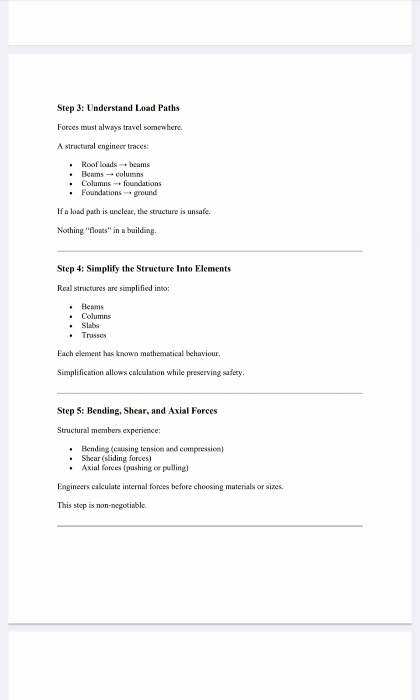Step 4, simplify the structure into elements. Real structures are simplified into beams, columns, slabs and trusses. Each element has known mathematical behavior. Simplifications allow calculation while preserving safety.